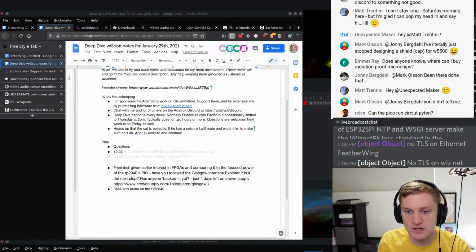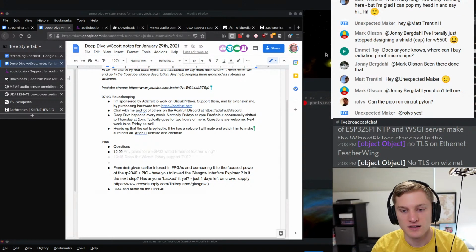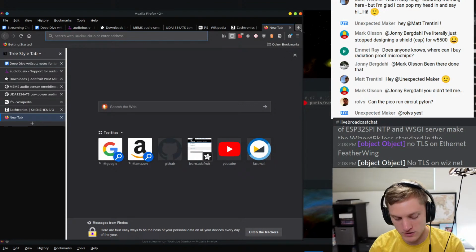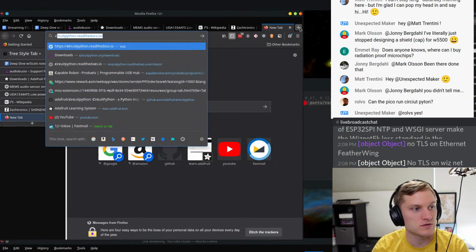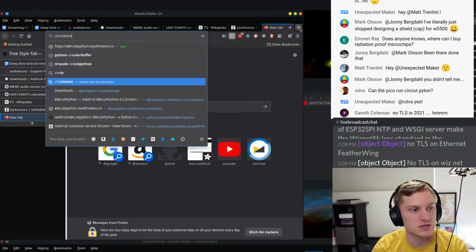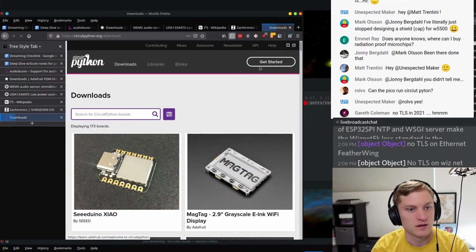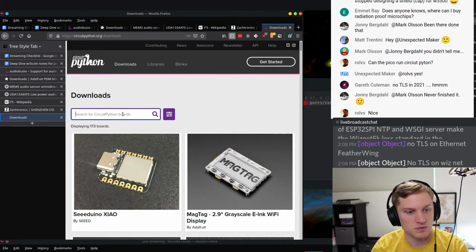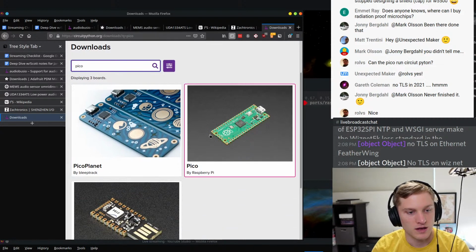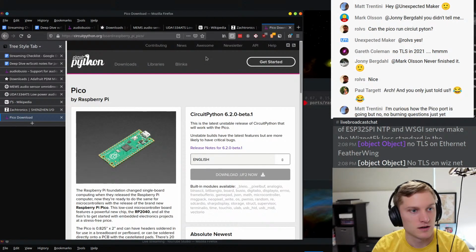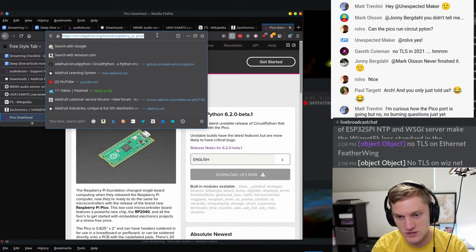Rolf says, can Pico run CircuitPython? Yes, definitely. If you want to run CircuitPython on your Pico, you go to circuitpython.org/downloads. And then you can search Pico. And you can find the Raspberry Pi Pico here. And since I have it pulled up, I'll put it in the chat too.